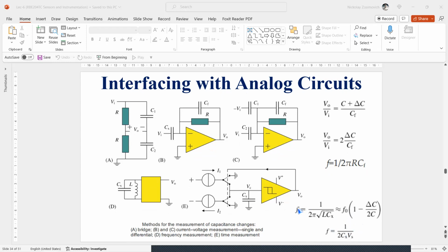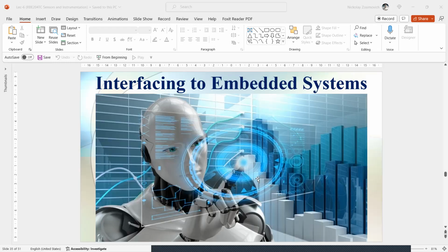The method yields accurate results because the frequency depends only on these fixed levels and the charge current. In the previous section, the sensing device is always a capacitor, of which a particular parameter, A, D, or epsilon, changes due to a measurement. The alternative to this so-called internal capacitance is the external capacitance that changes by human presence.